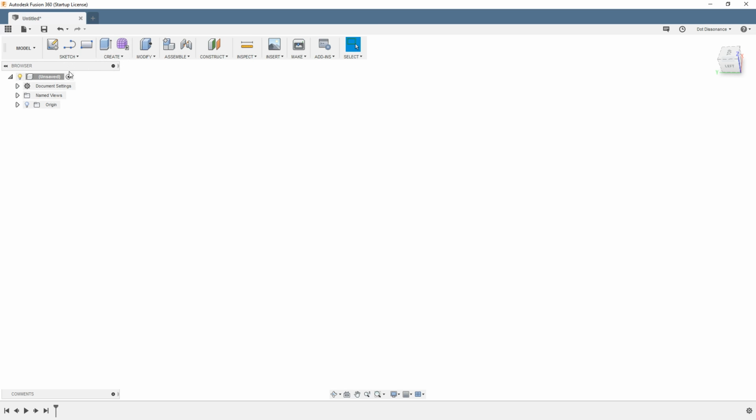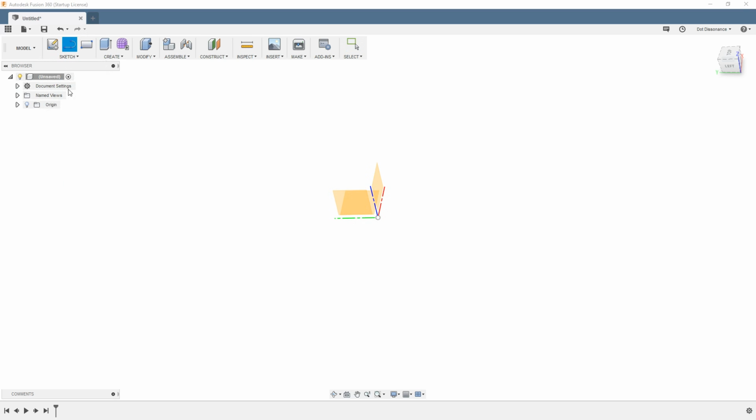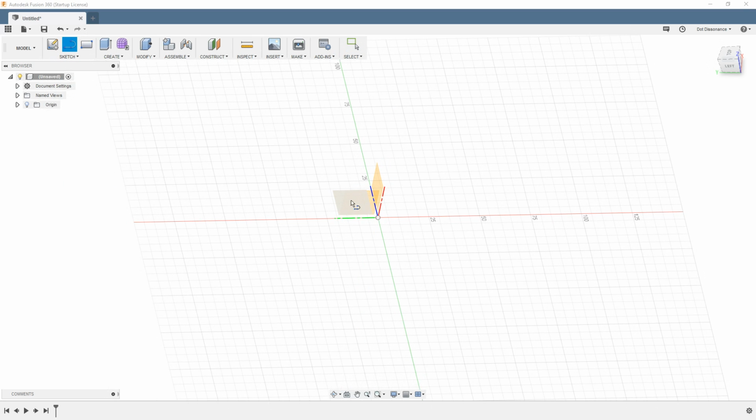But for example here, if I want to create a sketch, I'm telling you now to go to sketch and then pick the plane. Go to sketch, pick the plane, and then draw a line. Go to sketch, pick a plane, draw a circle. This kind of a pattern, okay? I could skip a step and just go sketch. I don't say create sketch, I just say make a line. As soon as I hit line, it automatically says, well, pick a plane, please, because in order to have a line, you need to have a sketch, and for a sketch, you've got to have a plane.